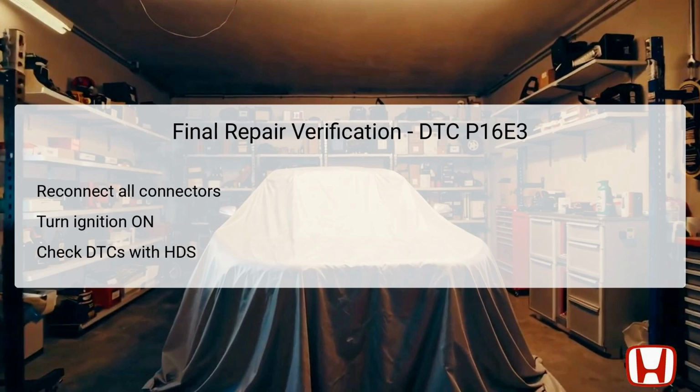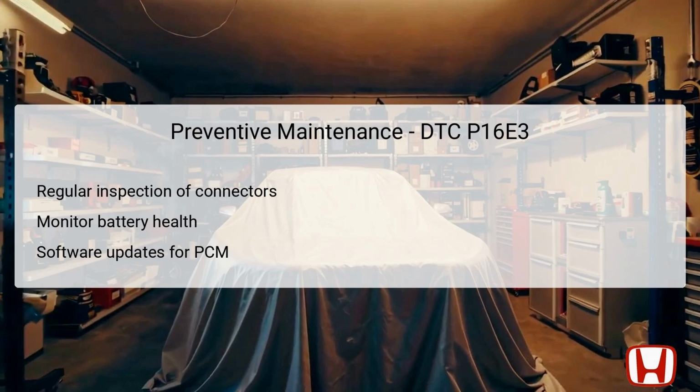If any fault codes persist, especially related to previous issues, further investigation into underlying problems may be necessary to restore full functionality. Preventive maintenance is essential to prolong the life of the vehicle's components and avoid issues like DTC P16E3 in the future. Regular inspections of electrical connectors, especially around the battery and PCM, help to ensure that they remain secure and free of corrosion or damage.